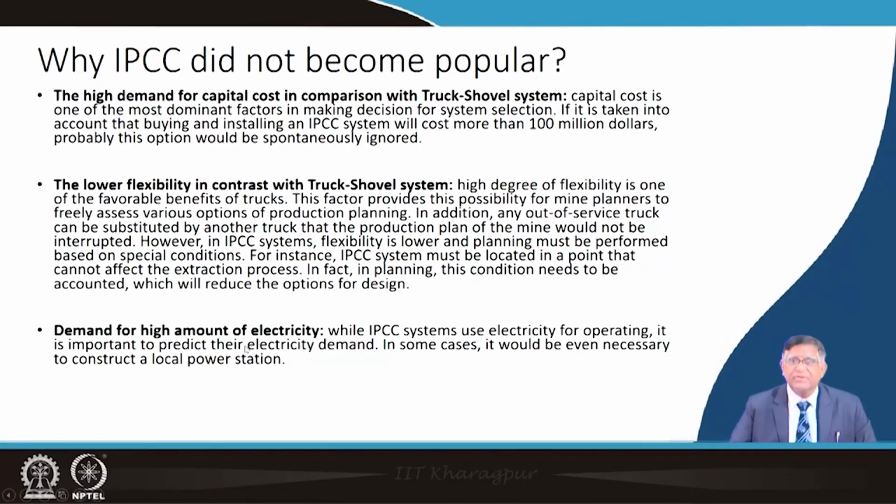Then there is lower flexibility, because once that conveyor belt line is split and has to follow the face, if the mine strata is not properly maintained, then that conveyor belt cannot be reinstalled. It is not a flexible mode of transport. And there is a high demand on electricity; if your electricity supply is not reliable and available, there also you cannot use it.